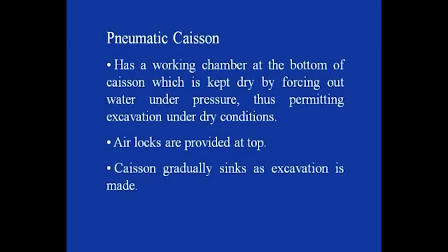Coming to the third type of caisson, it is the pneumatic caisson, and it has a working chamber at the bottom of the caisson which is kept dry by forcing out water under pressure, thus permitting the excavation under dry condition.